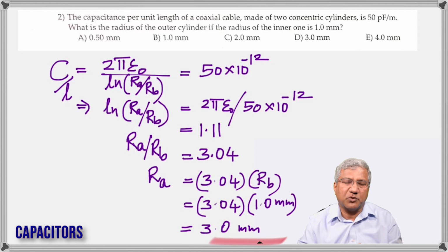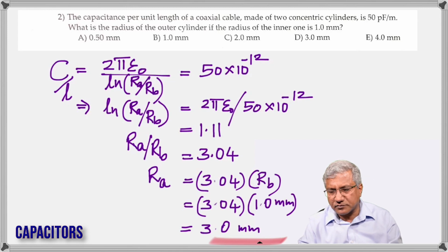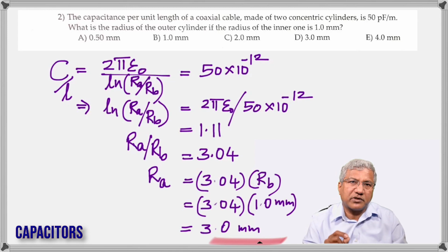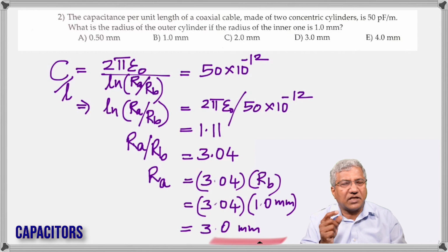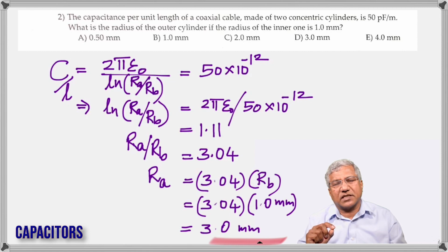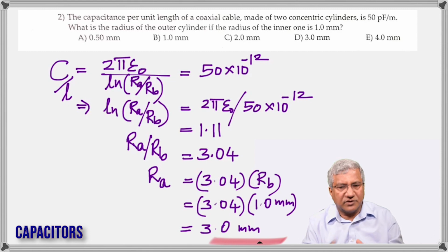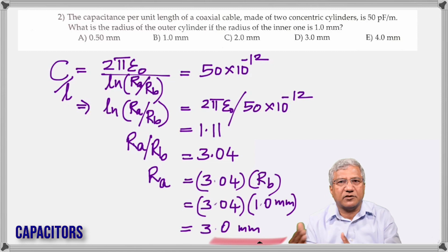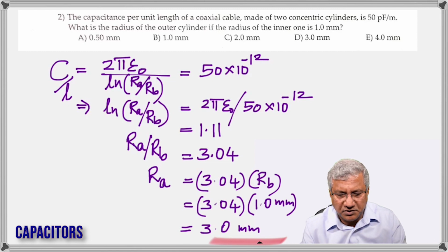So that is 3.0 millimeter. Hope you look at that math and work it out. But what is important here is what is given is not just the capacitance, it's a capacitance by length because of the units picofarad per meter. So be aware of that.